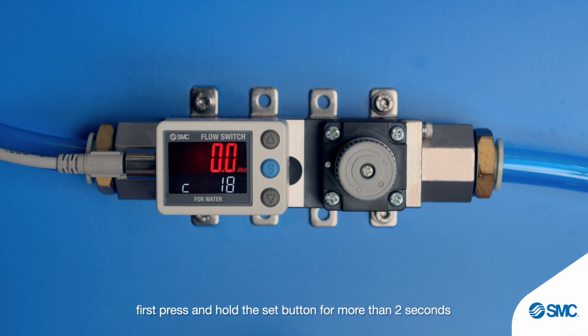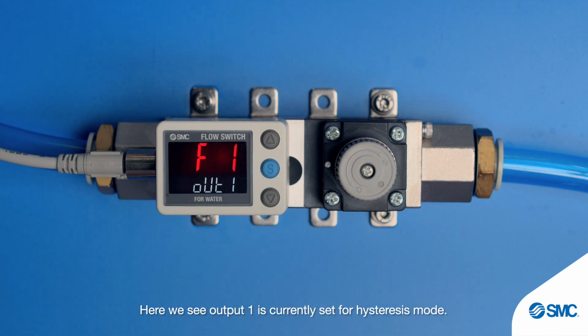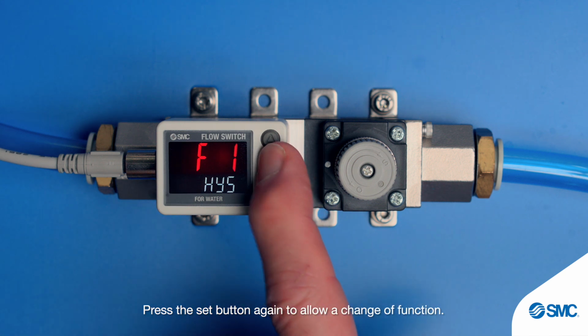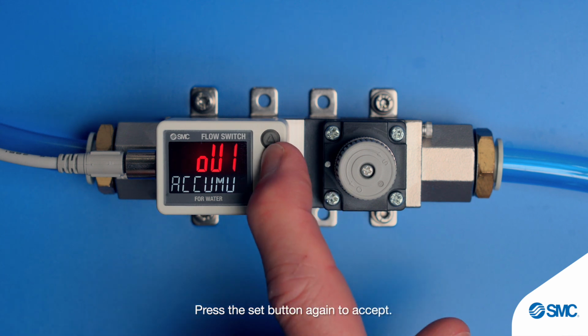set button for more than 2 seconds so that F1 is displayed. Here we see output 1 is currently set for hysteresis mode. Press the set button again to allow a change of function. Press the up or down button to select accumulated output. Press the set button again to accept.